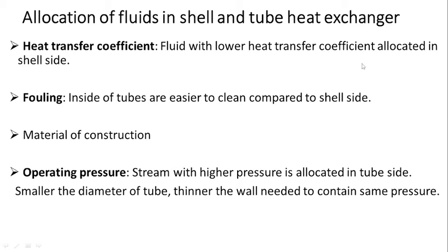And the second one is fouling. Fouling inside the tubes is easier to clean when compared to shell side. Fluids which have greater tendency to foul are allocated in tube side.